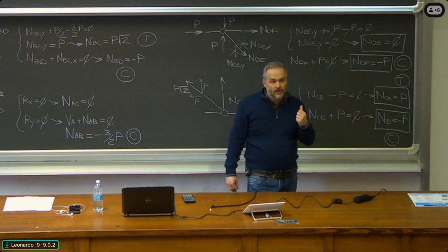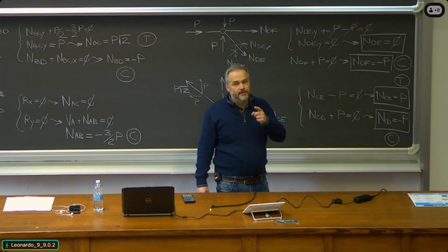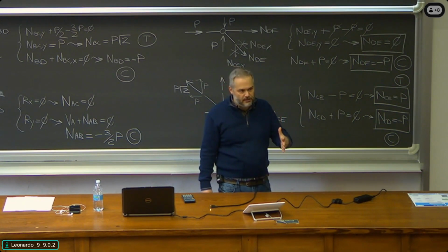But if a member is 0, we basically don't care about whether it's designed in one way or the other, okay? Anything will work well. For you at home, the question was, is 0 force compression or tension? Basically doesn't make any difference. If the force is 0, you don't have to specify whether it's compression or tension. It's simply not loaded, okay?